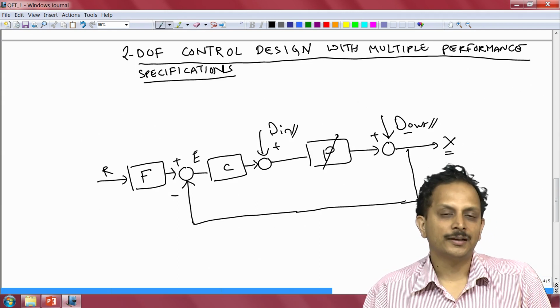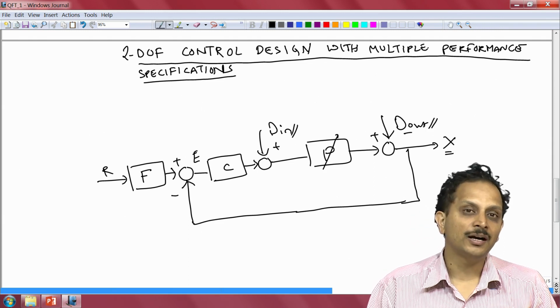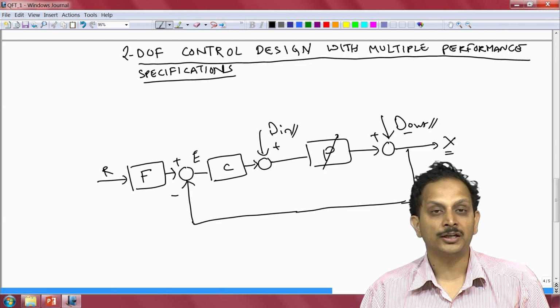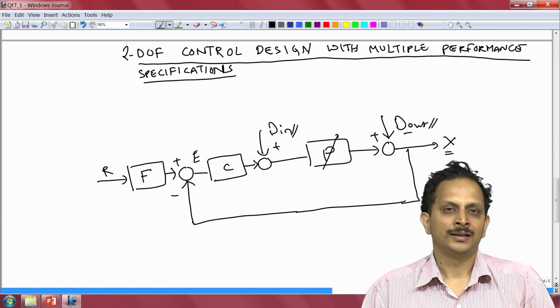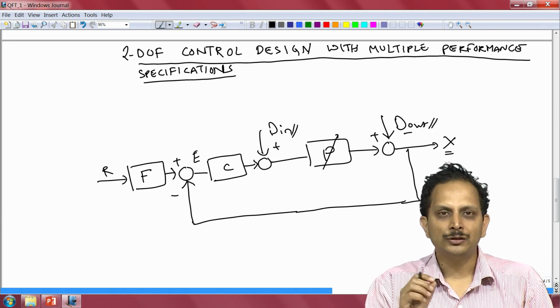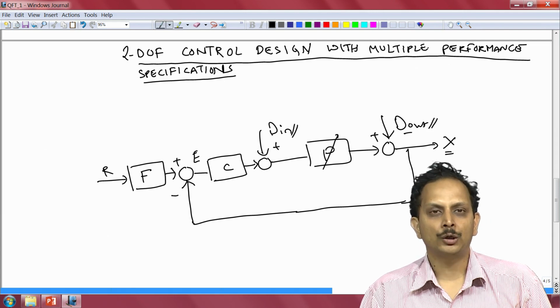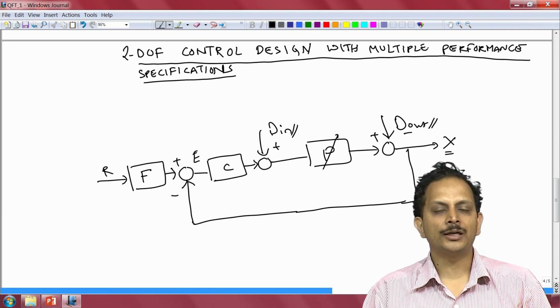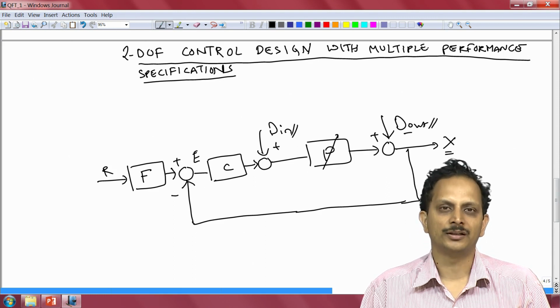It turns out that despite the fact that the Bode plot has significant advantages over the Nyquist plot in terms of the appearance of the loop gain, namely that the asymptotic loop gain looks like a bunch of broken straight lines, and the product of the controller and the plant gets converted to a summation operation when one uses the Bode plot for doing design.